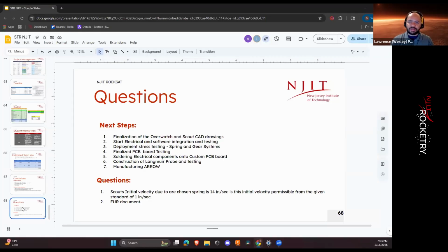But if you're trying to minimize the impact it's going to have on your experiment, maybe due to some electromechanical interference, you would try to minimize it, which is why I brought up something like an NTC thermistor or just something that can help you avoid the spike in the first place. But I do agree it's extremely low risk. I assume that's more or less when you're powering up your motor drivers or something. It's pretty common, but the only thing that's going to see it is the EGSE during check-in. All right. Okay. Perfect. Thank you. Absolutely.